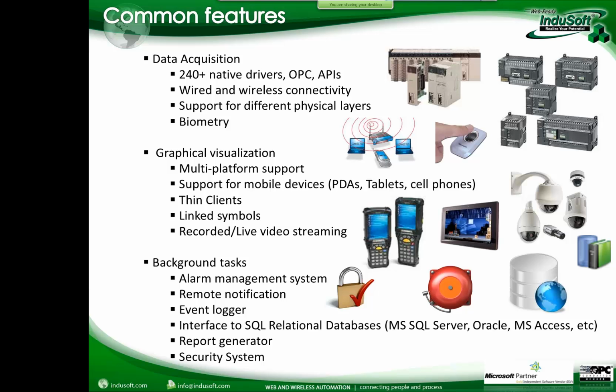For any type of Omron PLC, we have some native drivers and some specific drivers that we wrote using Omron APIs. If you're familiar with the CX Gateway, we have a driver that interacts with the CX Gateway, and even with the latest Sysmac Gateway through EtherNet/IP and all the protocols that are out there.